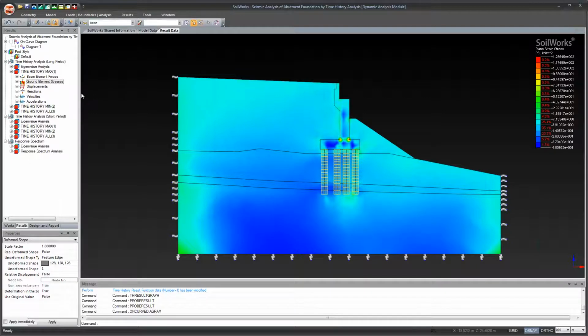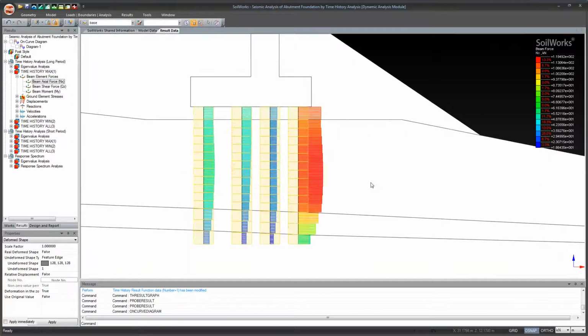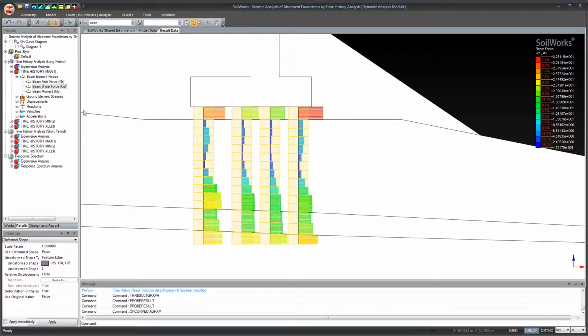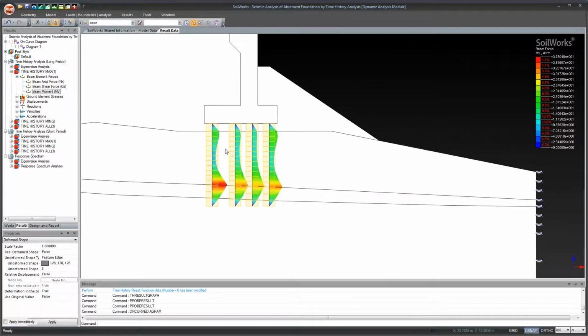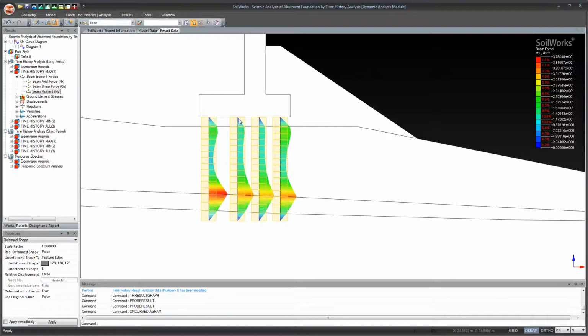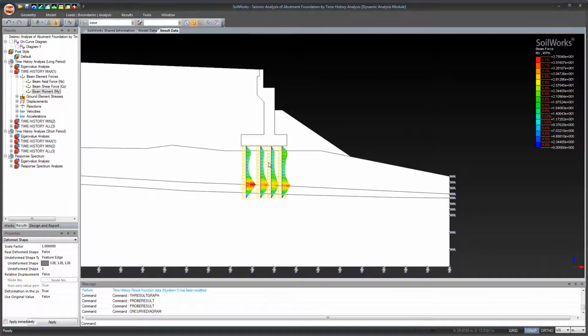In order to view that, just go to Beam Element Forces. So click on this tab here, and let me zoom in here for you, you'll be able to get your axial forces, your shear forces, as well as your moments for each of your piles. So something also that is very useful. Typically engineers will take a screenshot of this, and they'll have maybe some sort of spreadsheet with the maximum and the minimum values. They'll have that in their final report.